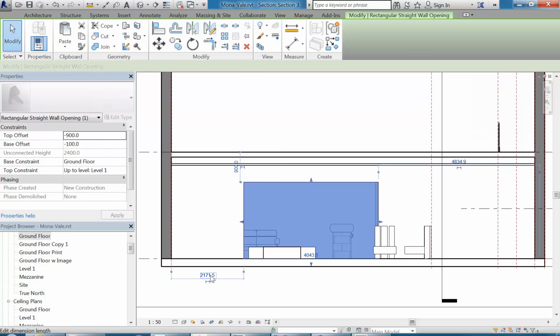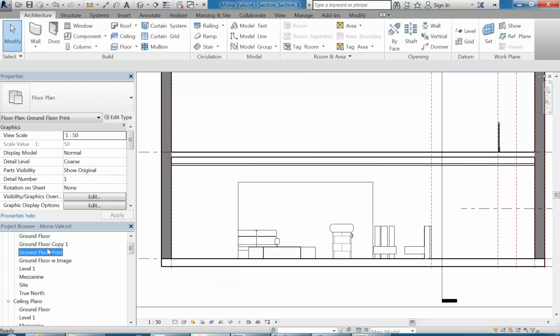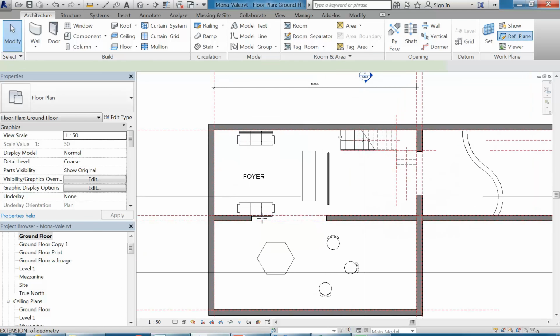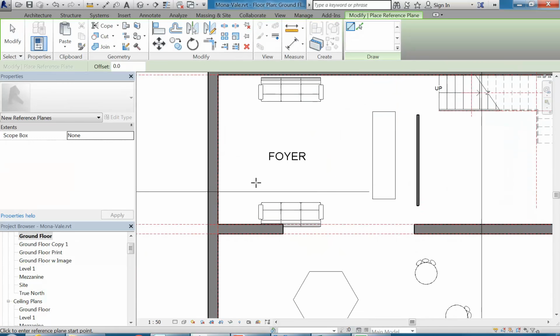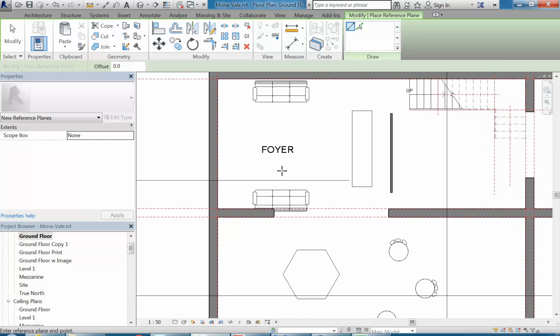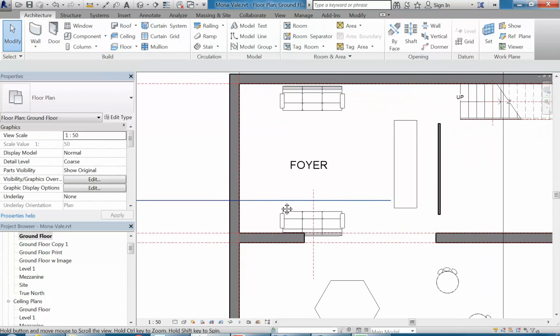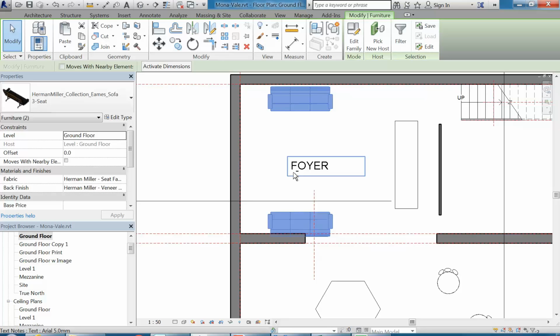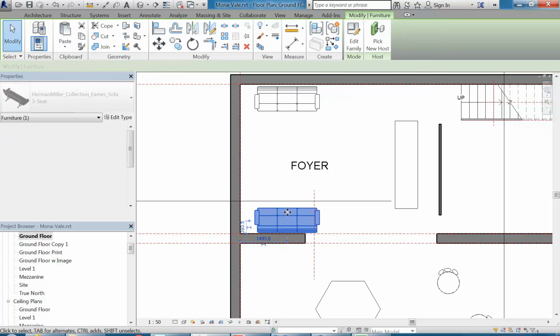So then you have the dimensions on the side, and you can use those just like anything else to change your measurements. But again, notice how it's moved the whole thing, and this is where openings can be a bit fiddly. But again, like a lot of things in Revit, if you put in reference planes to do your measurements, it makes things much, much easier. So I can put in maybe a plane out there, and I might think, well, these lounge chairs, this one actually is probably going to move later anyway, but for now I'll just move it across and maybe get away from the wall.